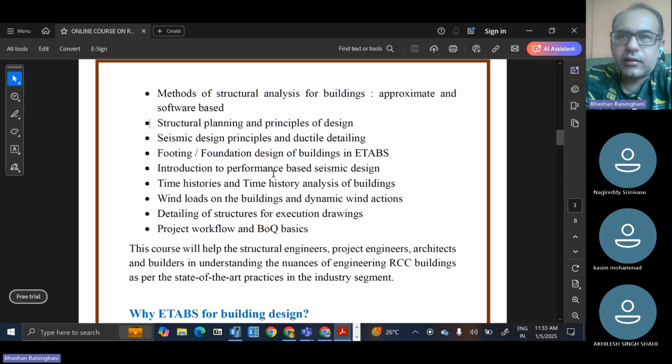So the geotech engineer has to be onboarded, or you discuss with them what parameters I should put, how much depth is the fixed depth which will go inside the soil, and what will be the above-ground height of this pile, which will act as a column.